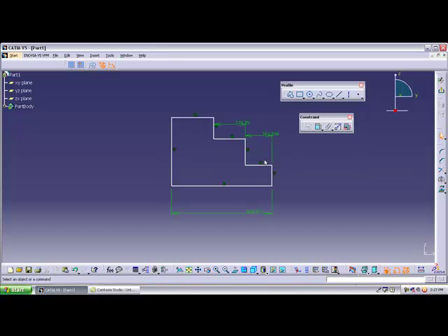That adds to 900. If you give this dimension as 500, does it obey the rule? These three lines add up to 900 and this line is 700. Is it possible? It's possible only if this line is not vertical, but it should be this shape only, and the dimension should not be moving. So for this, what do we understand now? To make it fully constrained, if you compulsorily want to give this dimension, what happens here?